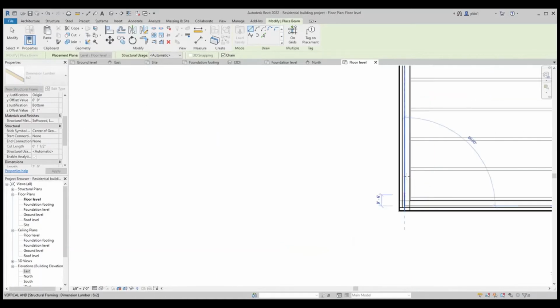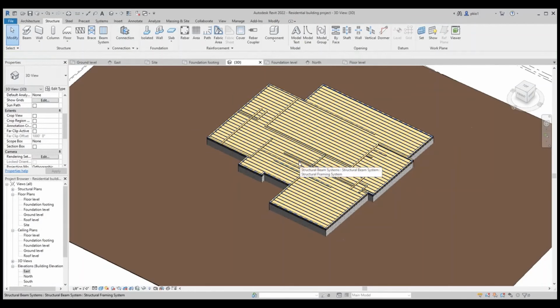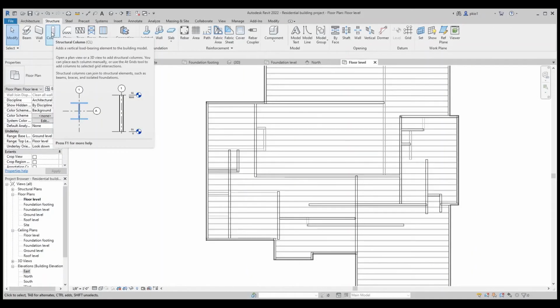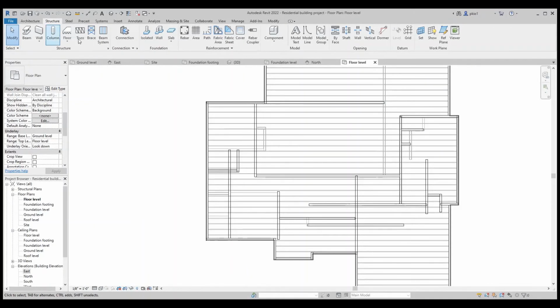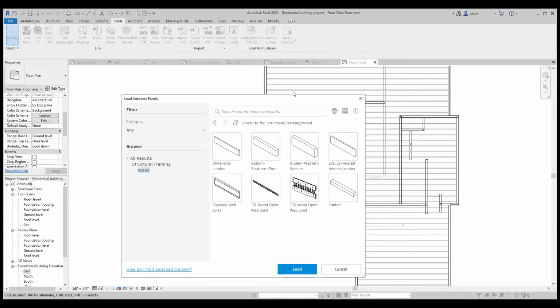And we're back to the beginning. So we have some internal walls and the external wall. After the bottom plate, the next thing we have are the studs, and we use the columns to place the studs. We'll go to the floor level. We need to insert the stud material first. So we go to insert, load Autodesk family, structural columns,